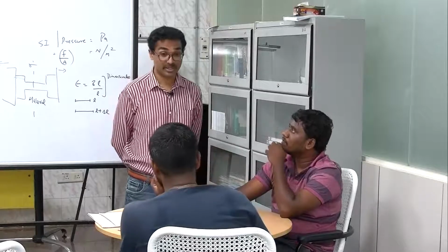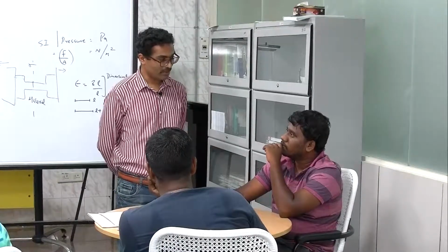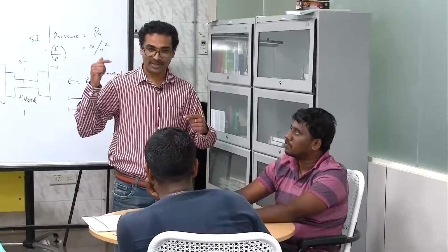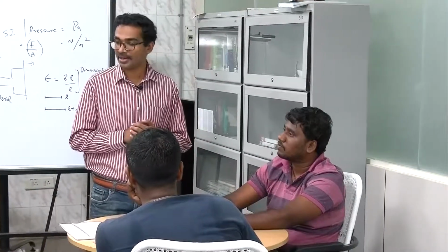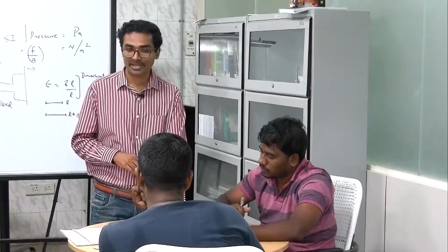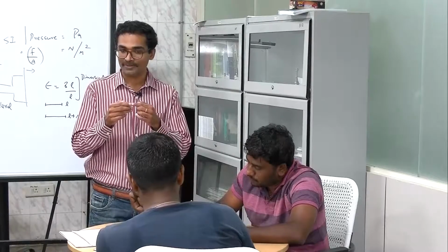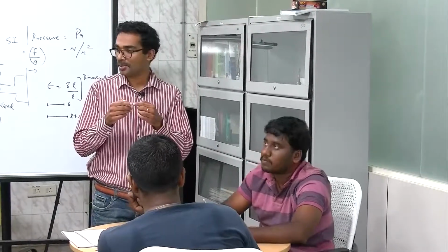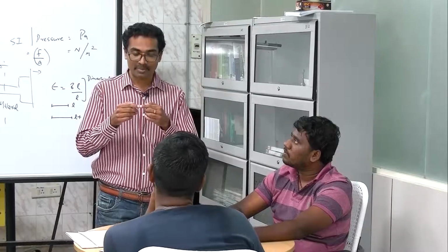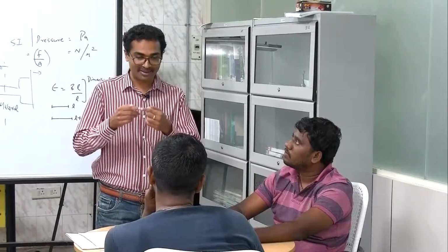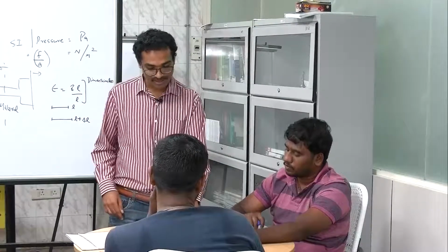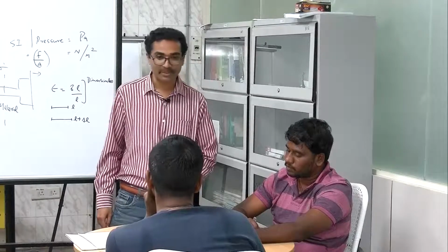Now it turns out that fuses, right? You know what the mechanism of fusing is? Electrical fuses, you know. So whenever there is a sudden increase in the current, the fuse goes off, and that has to do with this low creep resistance. So it's usually a metal wire. You run more than a certain amount of current through it, so the temperature goes up suddenly, and because at such high temperatures it cannot actually retain its shape, it starts sagging and snaps. So fusing basically is made possible primarily because of this low creep resistance.